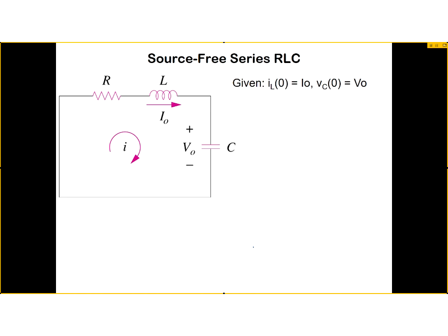it's okay. So we're going to start looking at the actual circuits now. The first one we're going to look at is source free. What makes it source free? No independent sources, right? And it's going to be a second order circuit because in this case we have one inductor and one capacitor, and they happen to be connected in series. Okay, so let's solve this circuit here.